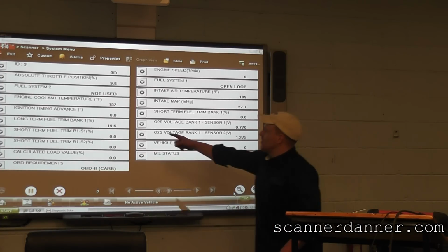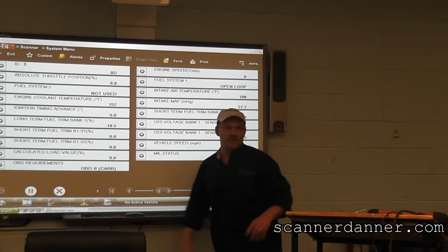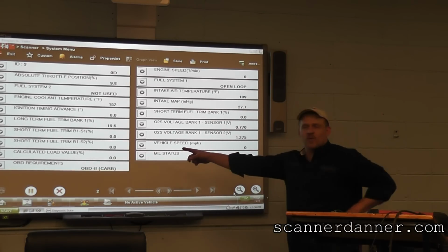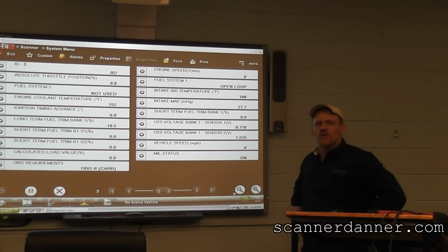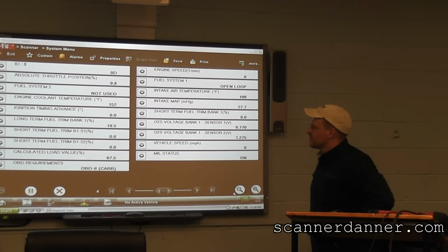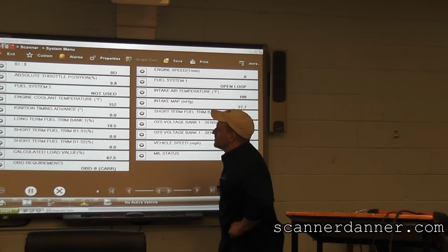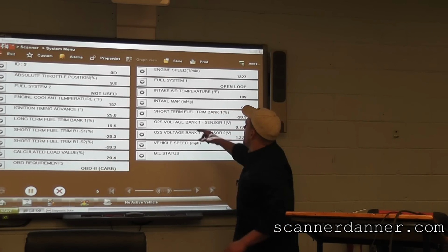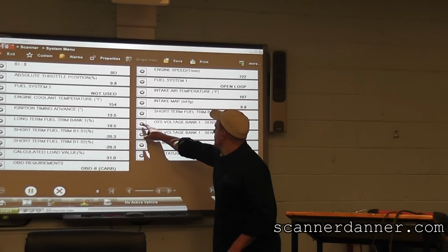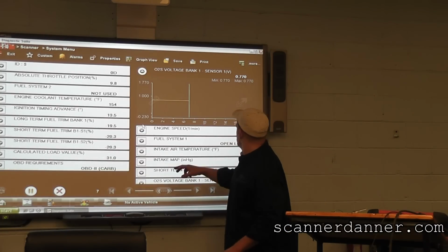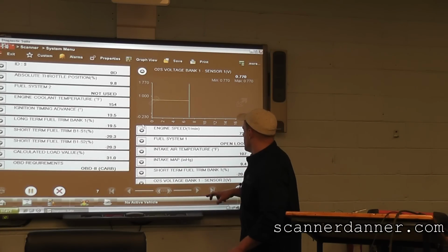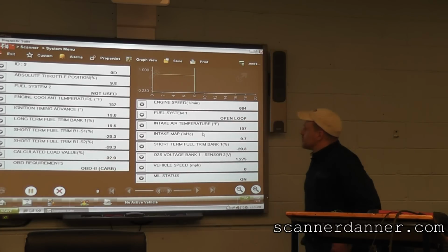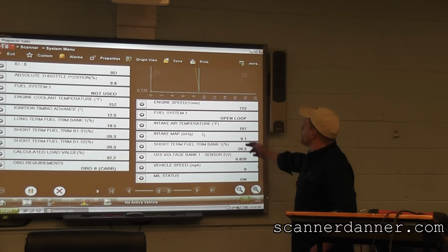All right, watch my long term here and short term. Can you start that for me, Jeff? Our calculated load, we were at 70-some percent before at idle. I expect that to be a lot less. Oh my. O2. Let's graph that guy. That's my upstream, and let's just watch these trim numbers for a second.